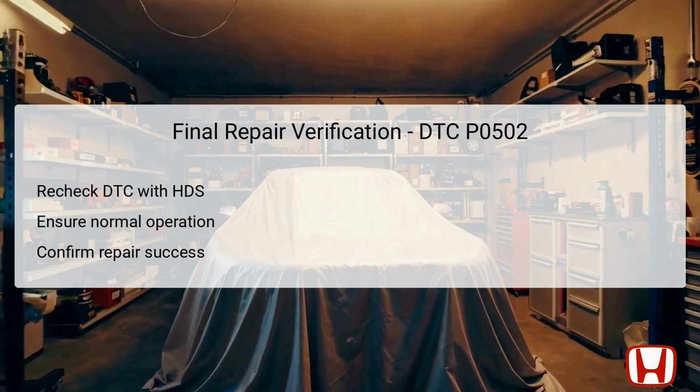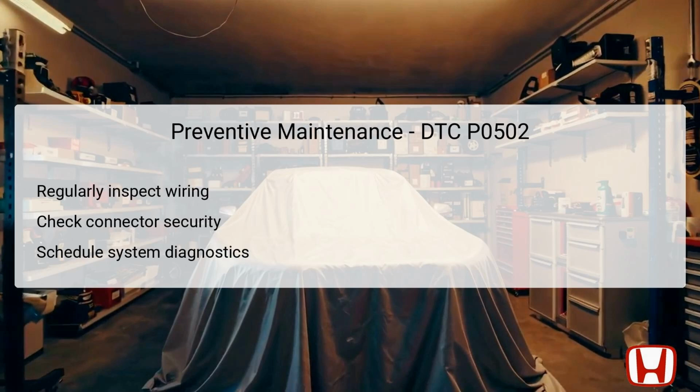vehicle's reliability moving forward. To prevent the recurrence of issues associated with DTC P0502, it's essential to implement a regime of preventive maintenance. Regularly inspecting wiring connections for signs of wear, fraying, or corrosion will help minimize future risks of open or short-circuit conditions. Moreover, ensuring connector security, especially around the CVT speed sensor and PCM area, can significantly reduce the chances of intermittent electrical faults.